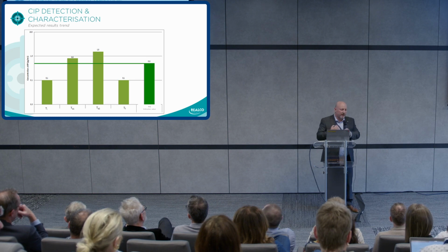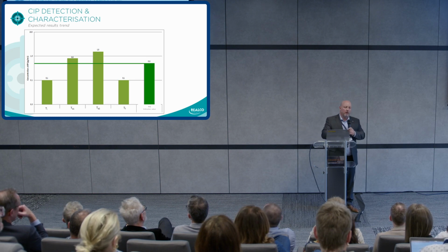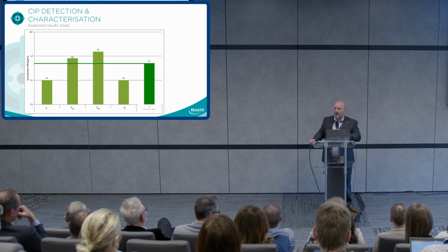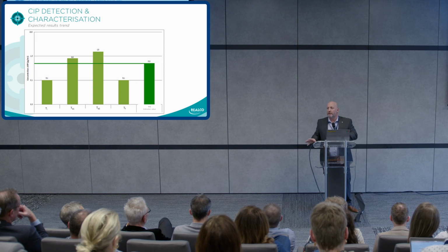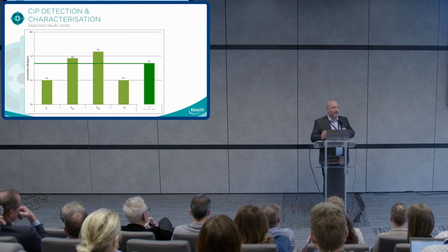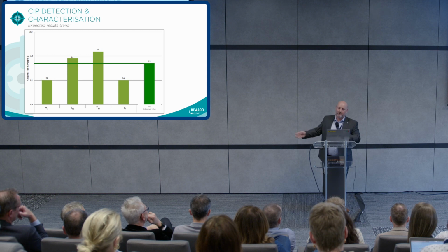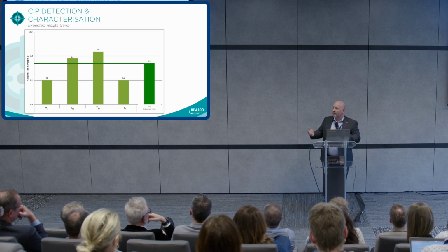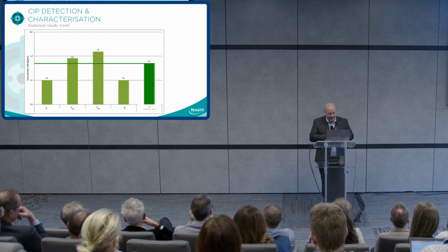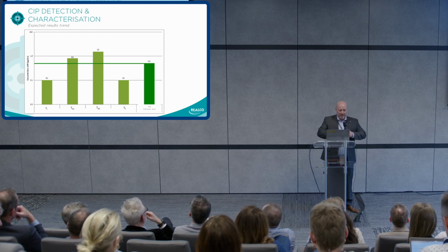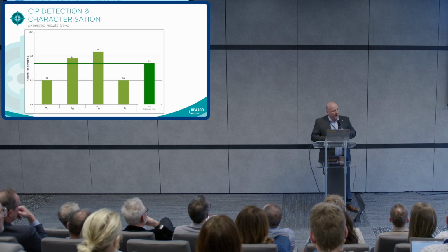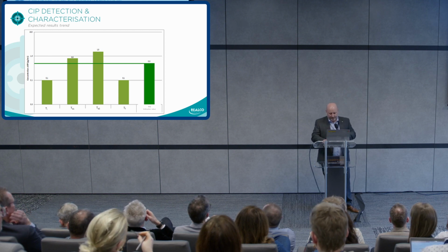So it helps us to locate the biofilm on that equipment, and we need to further investigate why this equipment is contaminated by a biofilm that is resisting the cleaning and sanitation we apply. Sometimes the initial water is contaminated. And I say, guys, do you know that you are cleaning and doing the final rinsing with contaminated water? What? So sometimes it's the case. It's very interesting, because it helps us understand the potential root cause of the contamination and locate the biofilm contamination.